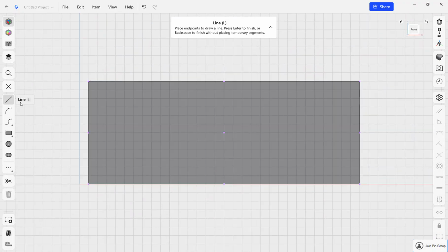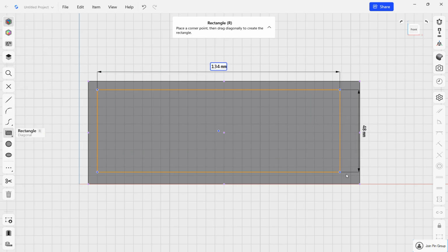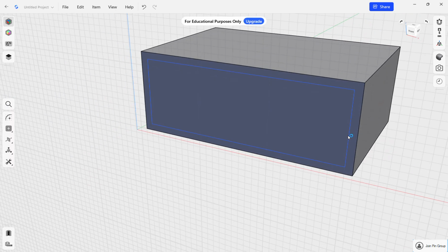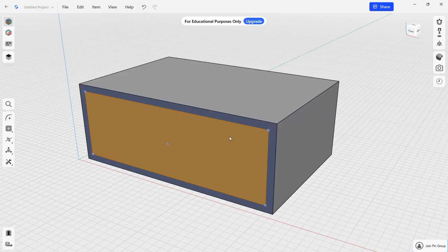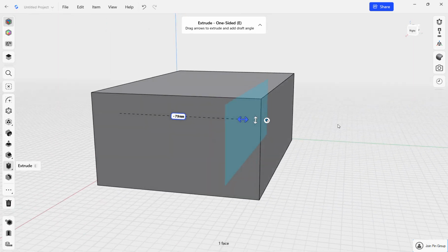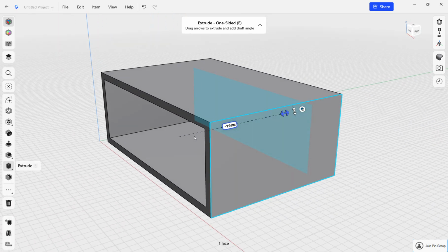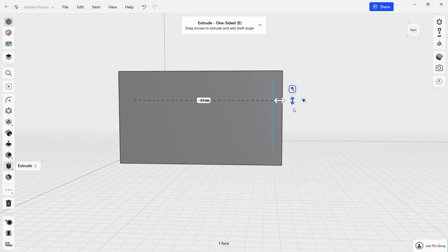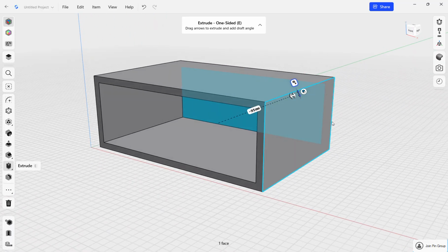So I could go on here and press sketch, and do exactly what I did before, and draw a rectangle, and then exit my sketch, and again, look, we've got 2 different sections here. I could click on this part and push that into my object. Now we made this 100 back. If we wanted it to be a nice, similar object, these were 5mm apart, so I want to go backwards 95, and then all my pieces of imaginary wood in this case are exactly the same.